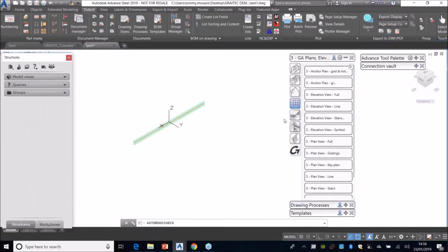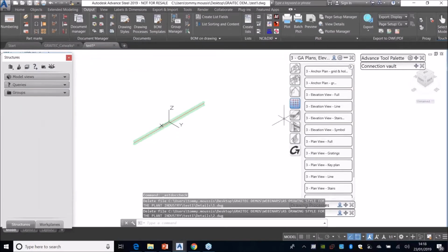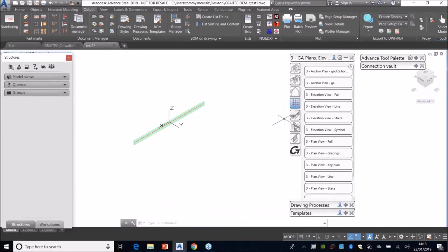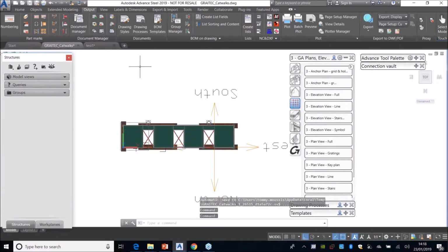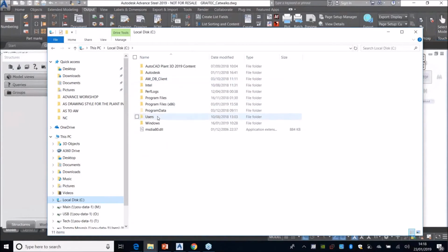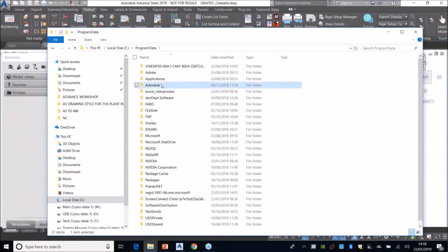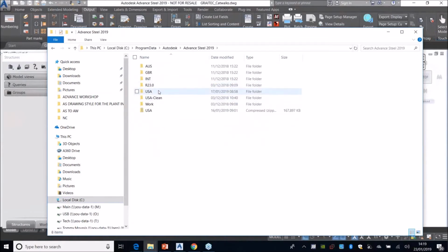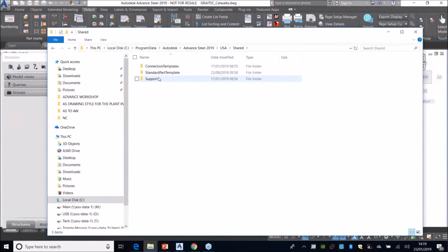Okay, so that's one way to manage just the generic prototype files after they've been modified. All right, it's much easier to just copy them locally to the model, so that if you're dealing with two different projects at the same time, of course you can have different prototypes linked when you're extracting the drawings, and you don't always have to remember to go in and manually change the prototype files at this location.